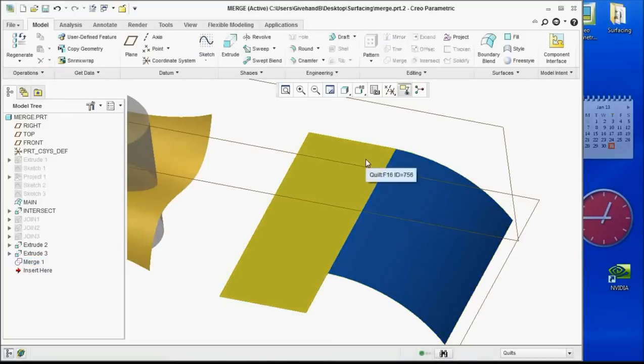If you've ever created a merge and you get a geometry check that says the merge was successful, but you created tiny surfaces or tiny edges, it's because you did not use the appropriate merging function. And what happens is the merge is okay, but when you go to solidify or thicken that, it all goes downhill quick. Okay, so this is a merge.